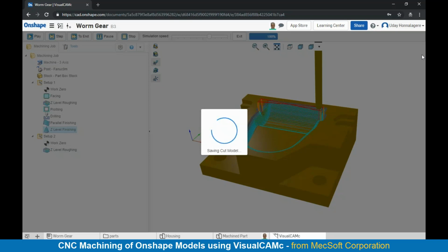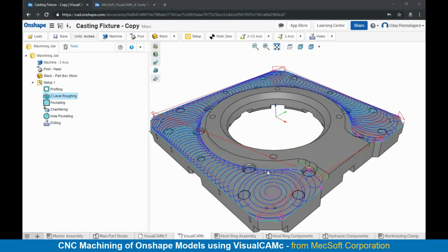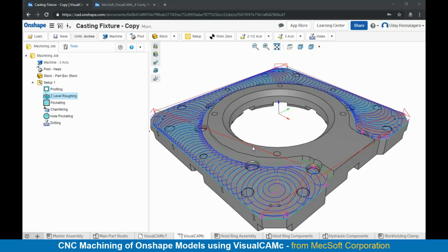the type of toolpaths that you can generate on different classes of parts or complexity of models. For example, here you're looking at a high-speed cut pattern toolpath that can be employed in a roughing operation, where you can generate very efficient toolpaths for roughing. It's generated by use of a constant tangential arc, so you can run it at higher feed rates, and it basically prolongs your tool life and reduces wear.